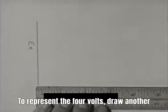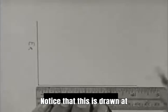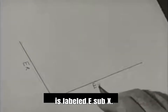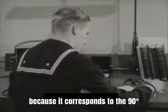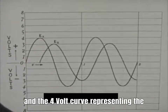To represent the 4 volts, draw another line 4 units long. Notice that this is drawn at right angles, or 90 degrees, from one end of the first line. It is labeled E sub X. A 90-degree angle is used in this case because it corresponds to the 90-degree displacement between the 3-volt curve representing the drop across the resistor and the 4-volt curve representing the drop across the reactance.